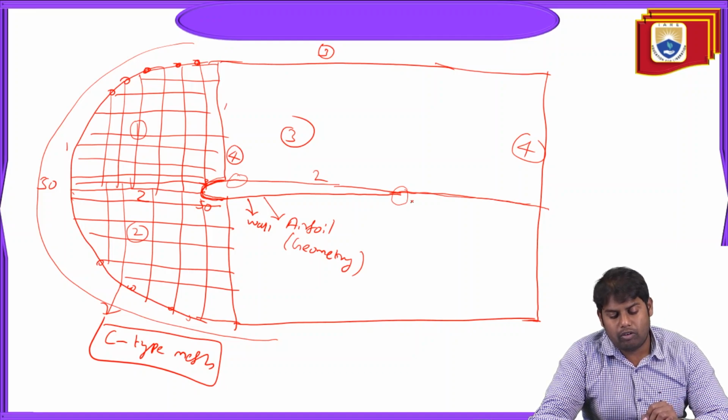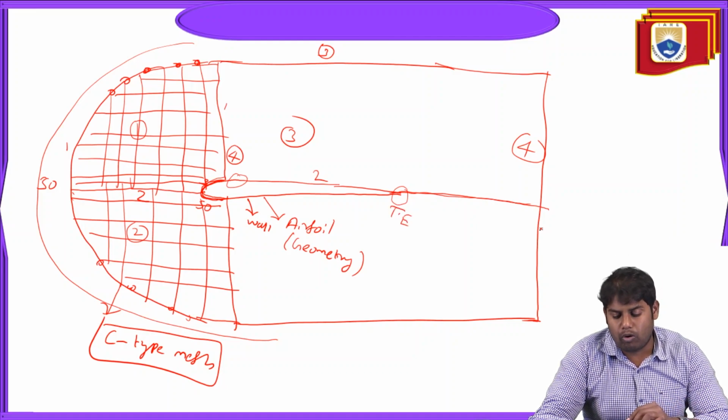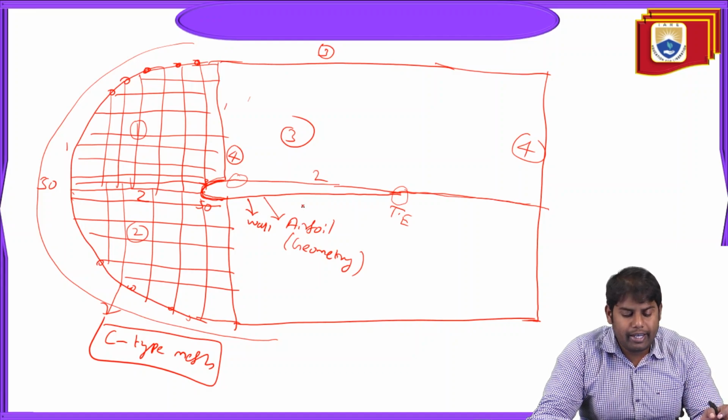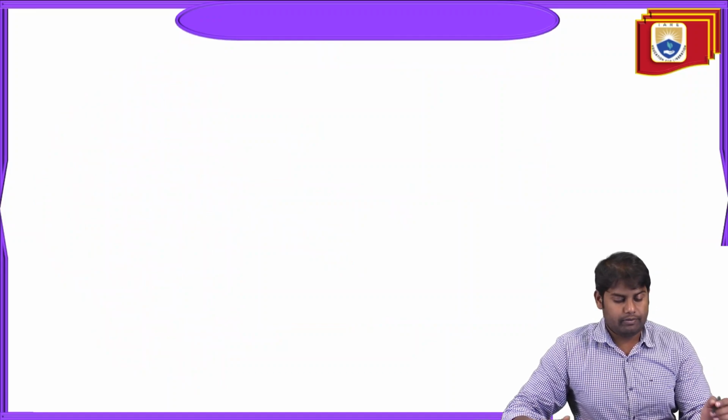Before, we didn't have any line drawn from the trailing edge of the airfoil to the boundary. When we have drawn it, it has divided the domain. This will be the upper segment and this will be the lower segment of the airfoil. The upper segment has formed the structured mesh entity by forming a closed entity. On the bottom also we can do it. Now by creating these lines, what we have done, we'll see in summary.